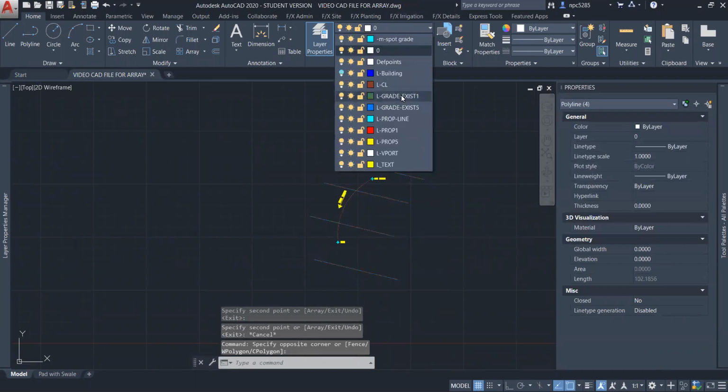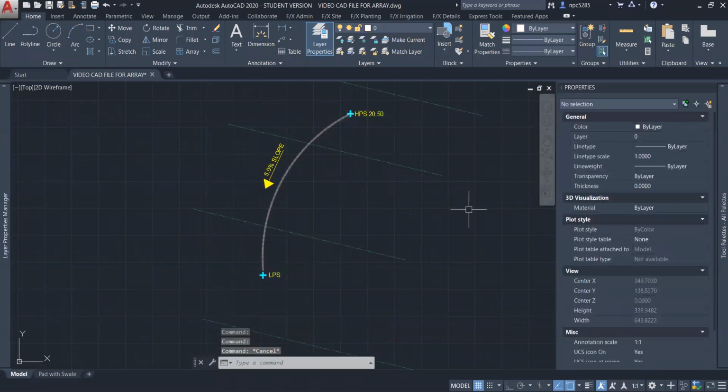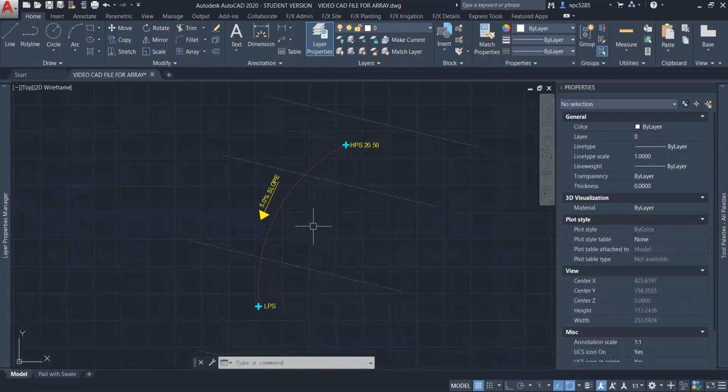Those are a little bit irrelevant once you get to the point of defining. You might gauge your LPS or your HPS, your first number, based off of where it sits amongst existing contours, but you're going to utilize the skills that you gain from the swale exercise, like the road and crown exercise, and any lecture material to figure out how you're going to place those and measure for them and draw your contours for them.